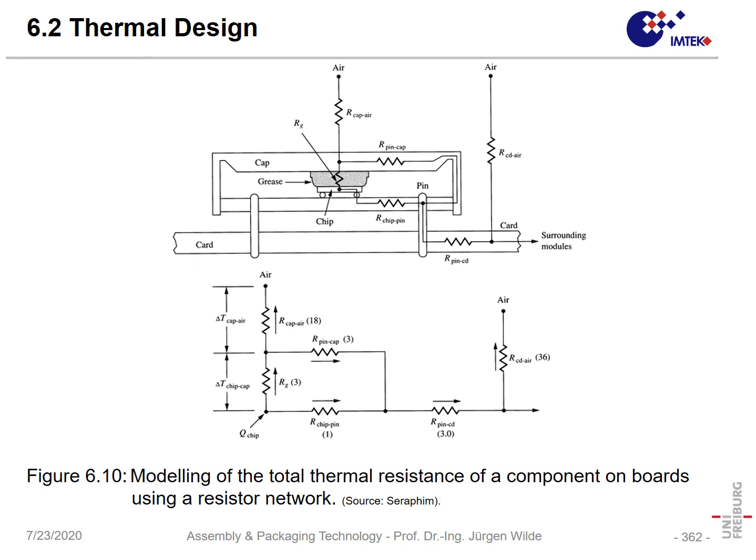Of course, you could say, yes, here you have thermal ground, and here you just put your voltage against ground, and in that way you have that thermal network, and by taking the resistances in parallel and in series, you can estimate what the total resistance is.